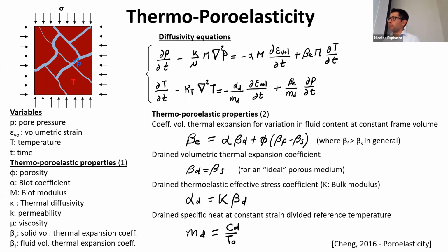Yeah. So will a rock also fracture due to de-stressing faster with fluid? Okay, so not quite. If you de-stress the rock, if you lower the temperature, the water is going to shrink more than the solid, and that will actually increase the effective stresses in the rock, and that may or may not make it fail depending on the horizontal stresses and in which direction you keep one of the stresses constant. That's what we're going to see later, but it does have an effect.